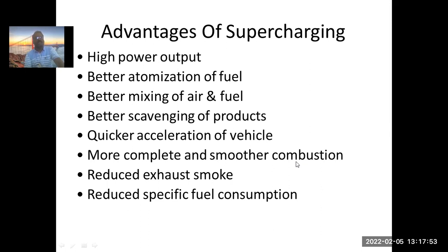Very good. Why? Because what we are doing is densifying the air. When we densify the air, that means the mass of the air is increasing. When we increase the mass of air, that means more oxygen. More oxygen means combustion is going to be complete. Obvious, isn't it? So the more the oxygen availability inside the combustion chamber, the more complete will be the combustion, and the more complete the combustion, the smoother it will be. Why it will be smoother, we will be discussing in our next chapter, that is combustion in engines.